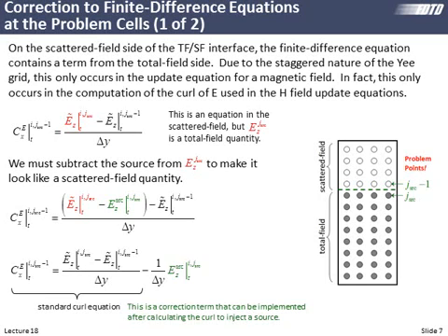We isolated our curl calculations, pulled them essentially out of the update equation, so we calculate our curl computations separately. And it's inside the curl computations where we have these spatial derivatives that reach out to adjacent cells in the grid. So it makes sense. This is where our problems would occur. This is where the corrections have to happen.